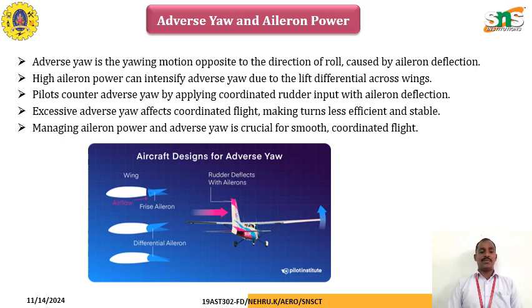Excessive adverse yaw affects coordinated turn flight, making turns less effective and stable. Managing aileron power and adverse yaw is crucial for smooth and coordinated flight.